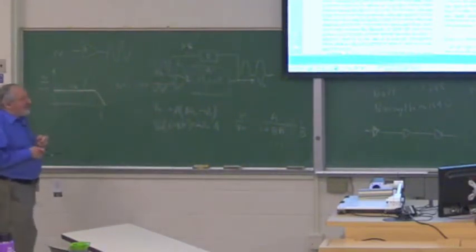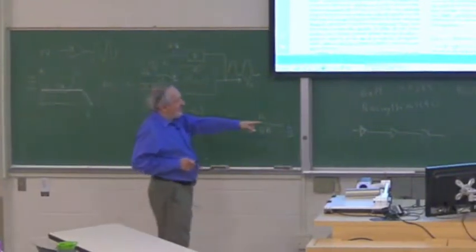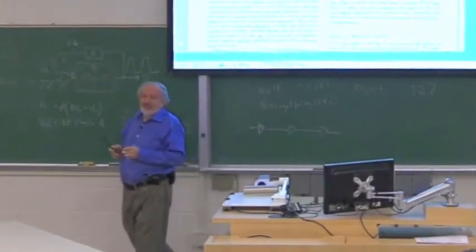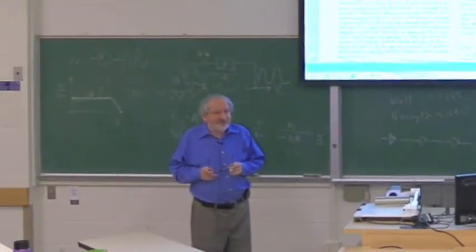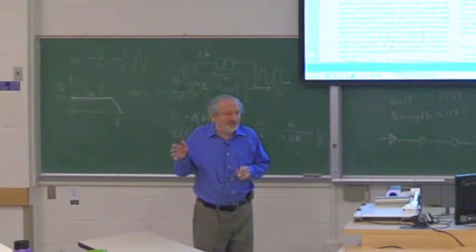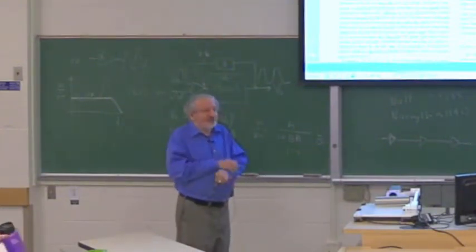So Black understood that and pointed out that not only would it fix the gain when you connect a bunch of amplifiers in series, but it will reduce the distortion a lot. And that's a very important thing. Think of audio amplifiers. Everybody is worried about distortion in audio amplifiers. But if you put feedback inside, they have less and less distortion.